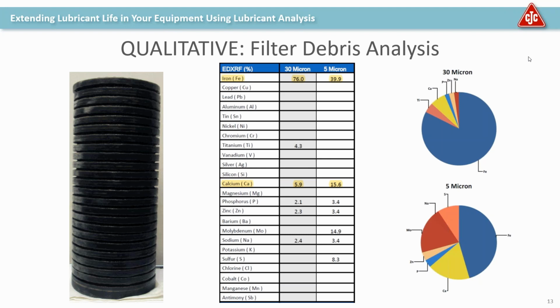As far as decreasing oxidation due to air entrainment, those types of filtration are geared at removing oxidation byproducts. So not necessarily due to air entrainment, but you will see similar chemistries from air entrainment as you will from water entrainment. It'll just be a different form of carboxylic acid. And these types of filters are meant to remove those byproducts. I think that answered the question. Justin, do you have any other thoughts on that one? No, that answered it well.